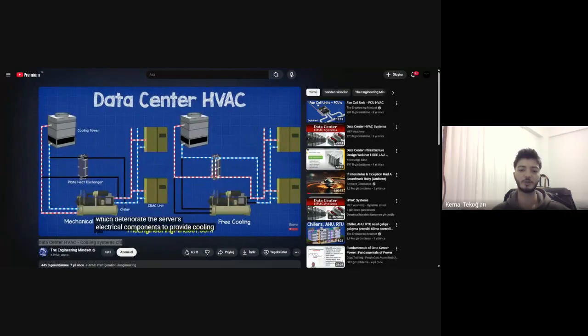To provide cooling to the crack units, you'll usually find a chilled water system using a traditional chiller. Depending on the location, some systems are able to turn off the chillers and use just the evaporative cooling capacity of the cooling towers for normal operation, then use the chillers as their backup if the cooling towers are unable to reach the set point.